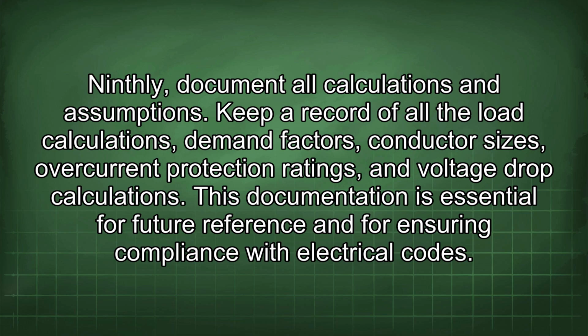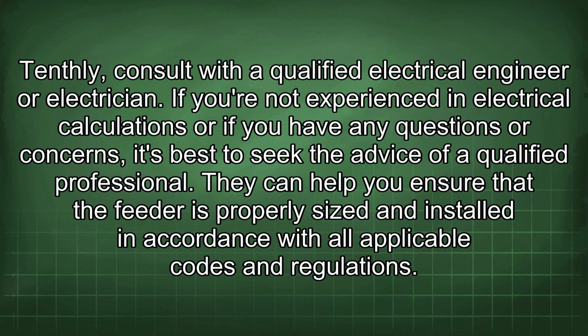Keep a record of all the load calculations, demand factors, conductor sizes, overcurrent protection ratings, and voltage drop calculations. This documentation is essential for future reference and for ensuring compliance with electrical codes. Tenthly, consult with a qualified electrical engineer or electrician. If you're not experienced in electrical calculations or if you have any questions or concerns, it's best to seek the advice of a qualified professional. They can help you ensure that the feeder is properly sized and installed in accordance with all applicable codes and regulations.